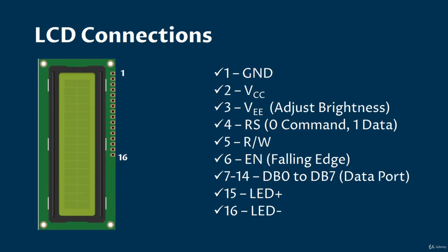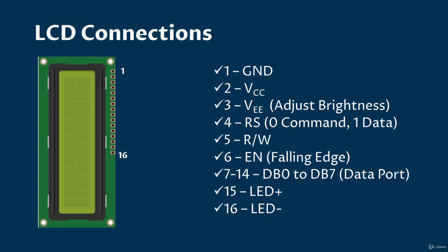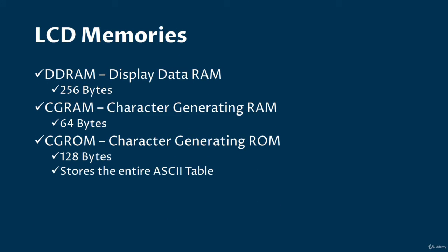Pins 15 and 16 are LED plus and LED minus. These are the pins of the LCD backlight. And if that backlight is on, then the LCD contents can be visible in the dark. And there are 3 memories: DDRAM, CGRAM and CGROM.